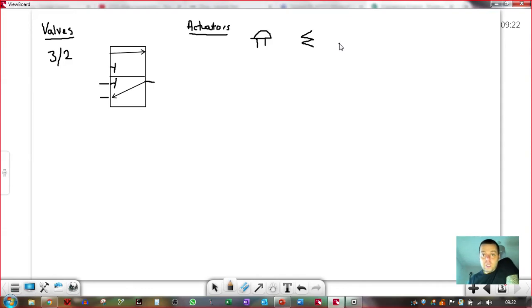You've got a plunger. So a plunger is a thing that detects linear motion, something striking it essentially. You've got a roller. So the roller detects passing motion, so linear motion but going across the way instead of straight in. You've got a roller trip, which is 2 wee wheels, so this one out to the right hand side kind of flops up and down, and again it detects passing motion, but it detects passing motion of something large. It's got a lot of displacement in it.